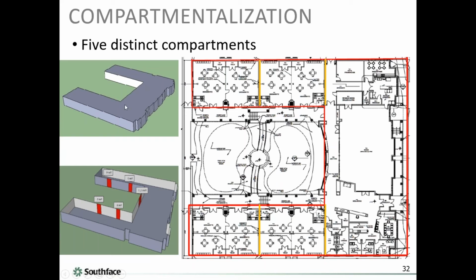This was a school we tested. Remember how big this school was? Like, yeah, I'll say around 22,000 square feet. These were 2 classrooms, if I remember, with a kind of a dividing wall between them. And these buildings had a sloped roof, but they were foamed roof line, and everywhere there was that orange line right there, there was a firewall that went all the way up. So they really were 5 separate compartments.